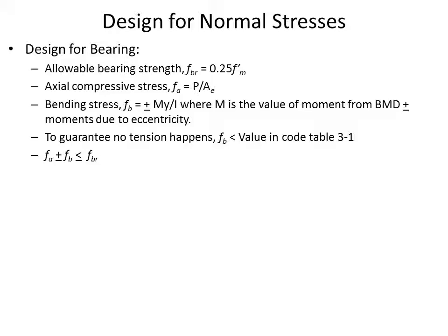And again, the bearing stress is only checked if you are having a bearing failure. So if you have a load resting on a plate above the wall and the load is not distributed, the load is concentrated. In such a case, you are worried about bearing failure. However, if you have a distributed vertical load from the beginning, you don't need to check for bearing. Here we are talking only about a concentrated vertical load. Okay? So that takes us to stability.